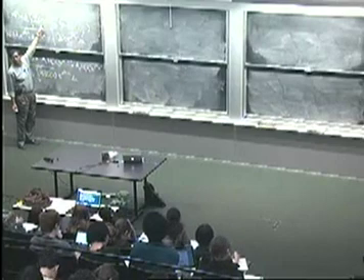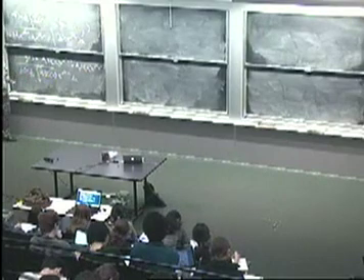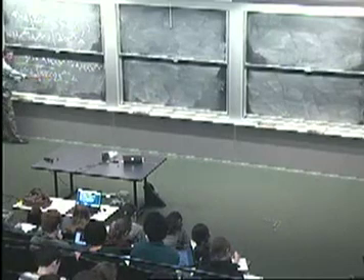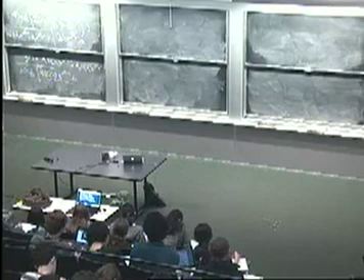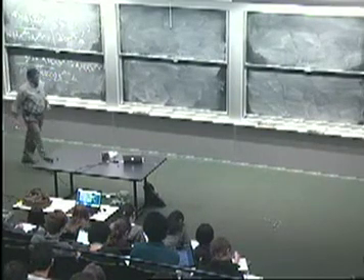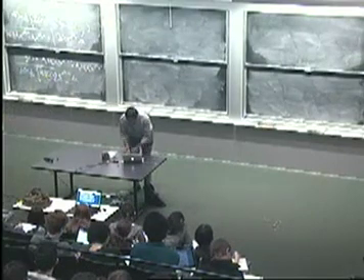The weights are given by the X(omega)s, or X(omega) d omega, if you want to think of it that way. So what comes out is the combination of responses to each of those. For each frequency, you multiply by the corresponding value of the frequency response, and do that for all the frequencies of the input, right? So this is just applying linearity and superposition.